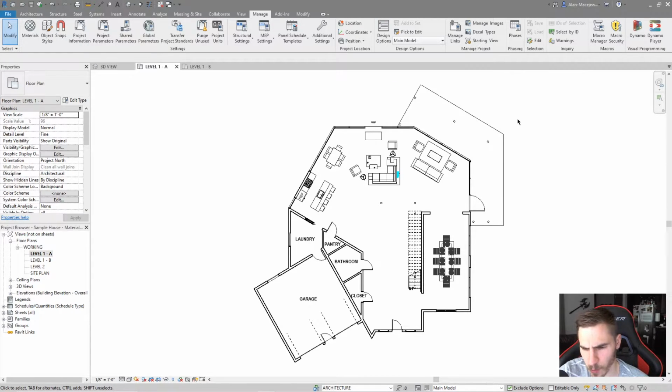Okay, all that makes sense, but what am I doing here? I'm essentially trying to make sure that the material of that element continues to populate the finish schedule, because that gutter, if it's a specific metal and that's the only place I have that metal, I want that metal to show up on my finish schedule, of course. But like I said before, if that object is only on a profile-based element within Revit, like a gutter, then it won't populate on a finish schedule because it's profile-based. I don't like it, but that's the way it is. So the workaround really is to take a cube and then paint a face of that cube, or really any element. And as long as that element exists within your project, that material will be populated on your finish schedule.